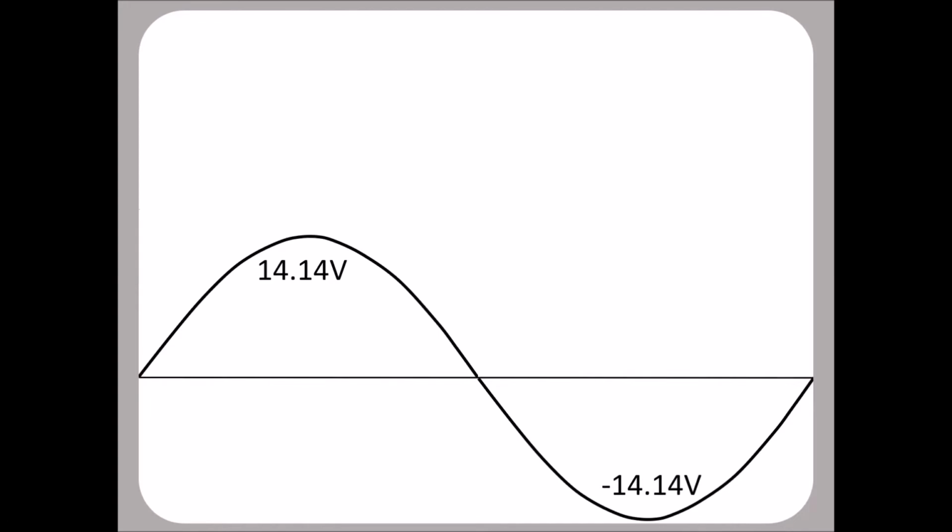The truth is, I want it to be operating so that the light looks no different to you and me than it did when it was with DC. So in this case, with that particular lamp, the current will follow the voltage up and down and go up to 3.5 amps. Now we want to look at the power.